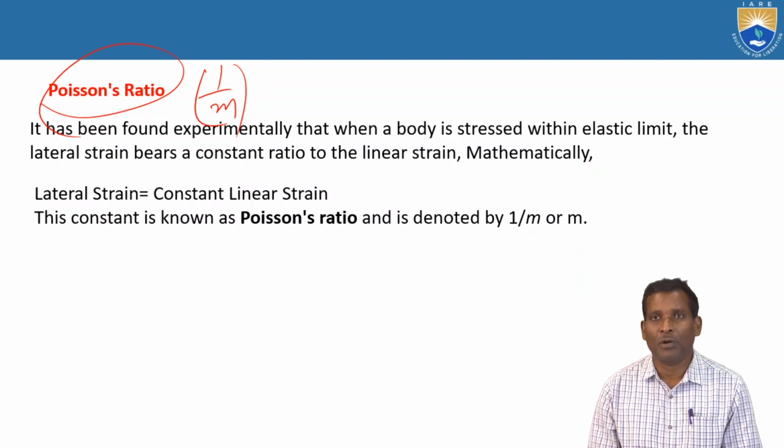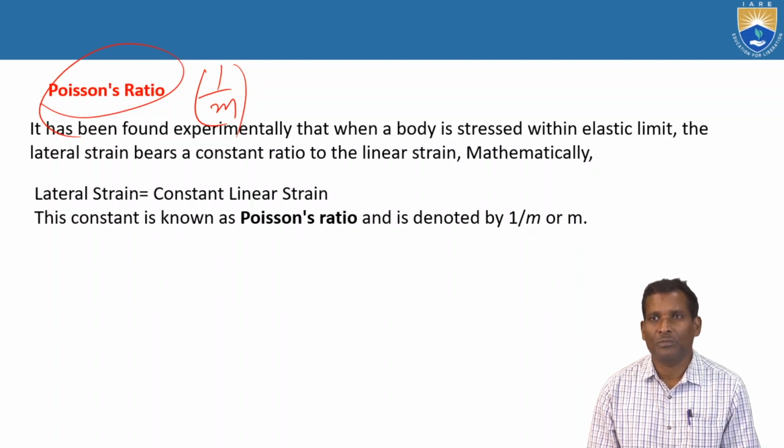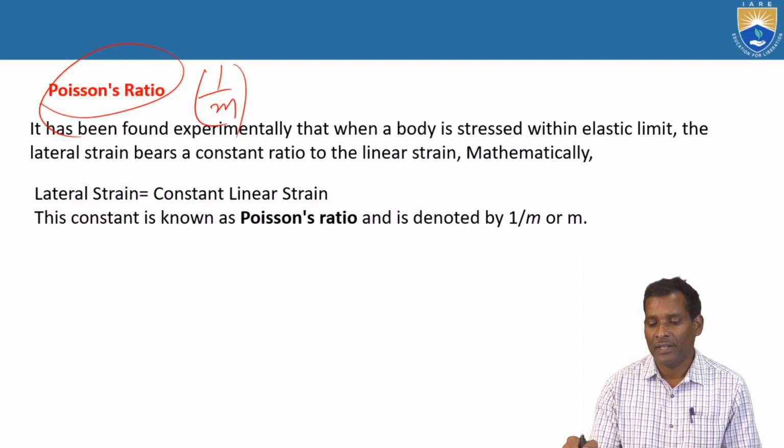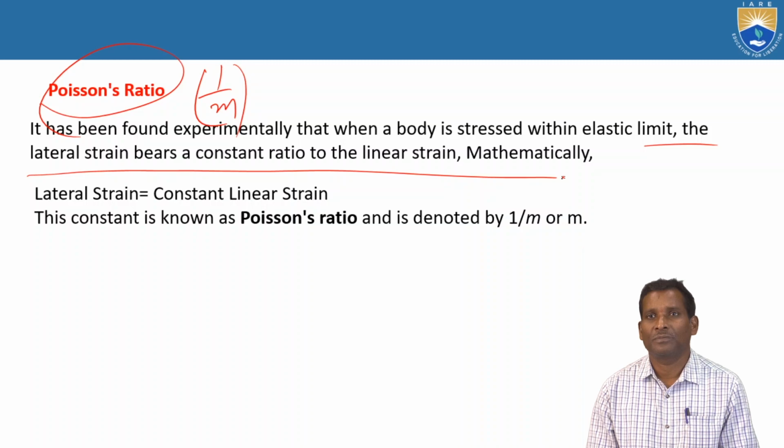It has been found experimentally that when a body or component is subjected to load, it may be a tensile load or a compressive load, within the elastic limit, then the lateral strain bears a constant ratio to the linear strain.